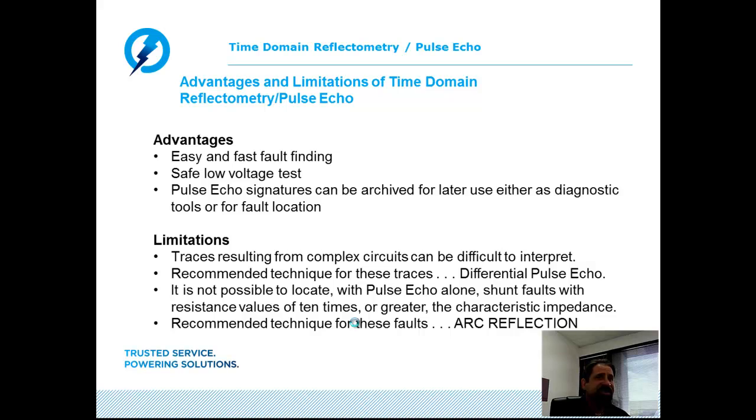All the time I'm using safe low voltage pulses. So I'm not stressing the cable. There's no electrical hazard to me in handling or using the time domain reflectometer. So it's good, safe, low voltage. I can use the time domain reflectometer anywhere from telephony cables, datacom cables, signaling and control, all the way up through low voltage, medium voltage, and high voltage electrical power cables.